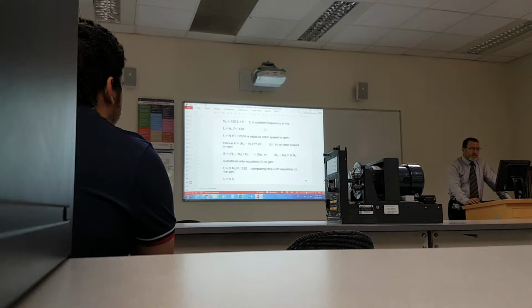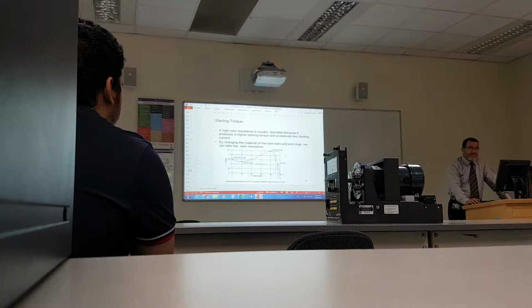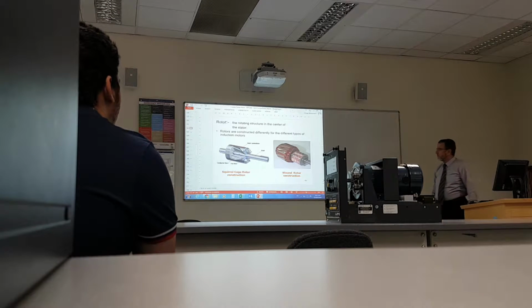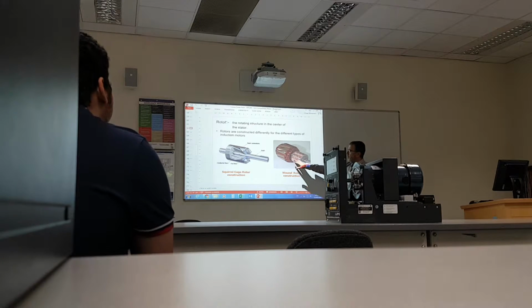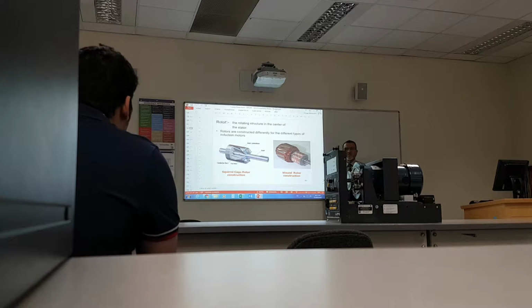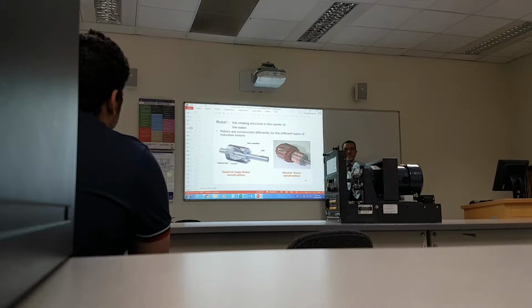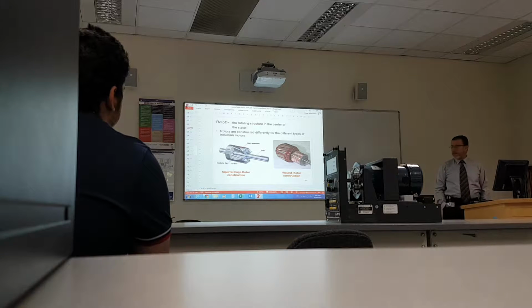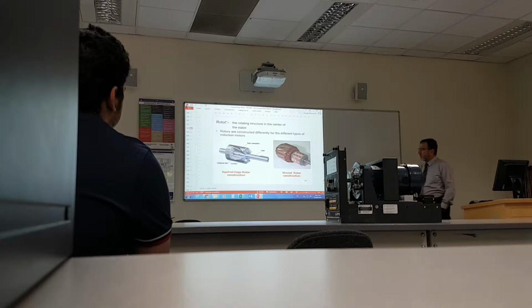Slip rings are there only for connecting external resistors, for 3-phase. So we're not supplying any current to the rotor.